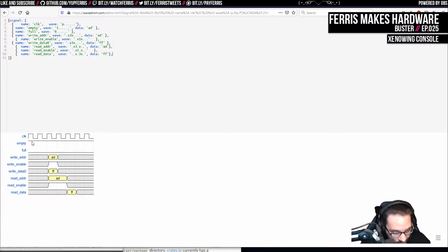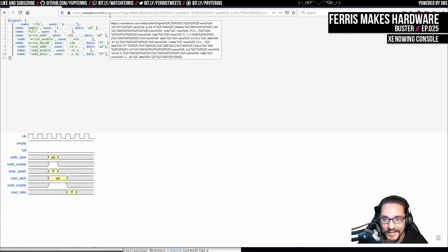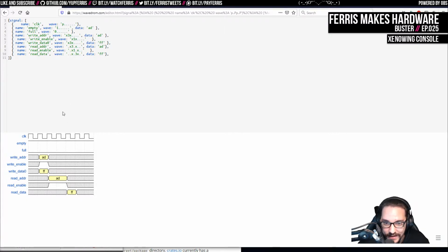So initially on reset, you have this full condition low because obviously the Fifo's not full, and then you have this empty condition that's high because it's initially empty. And let's say this has more than one element in the Fifo, and let's say 2 because that's the minimum that I basically support because of the memories. So if we just look at a write, let's say we issued a write. In fact, we can even move these back again. It doesn't really matter. And we'll do the same for the data. I like this tool because it gives nice diagrams and it's not that hard to modify.